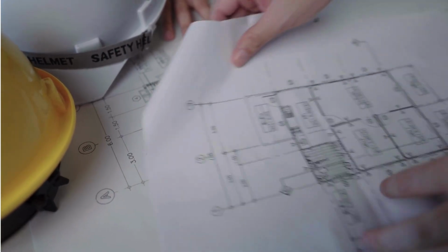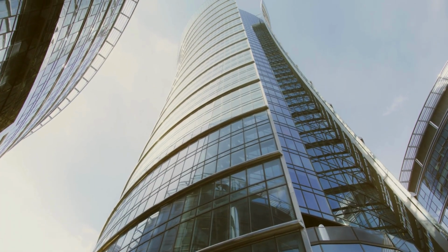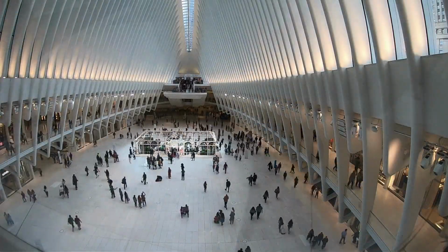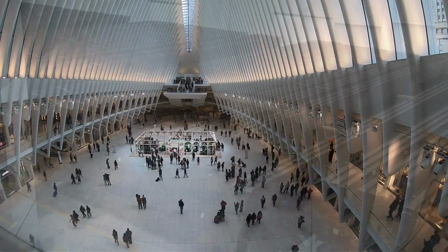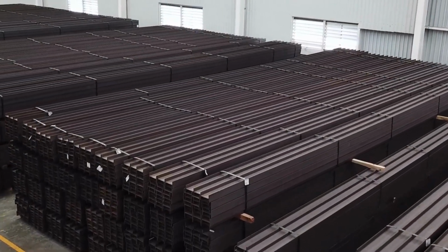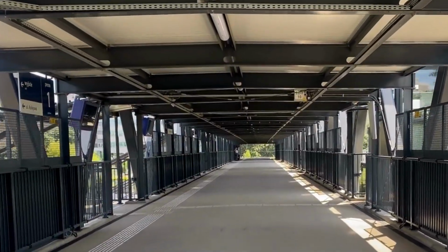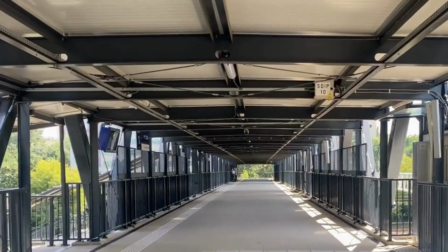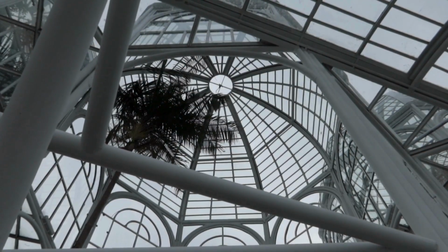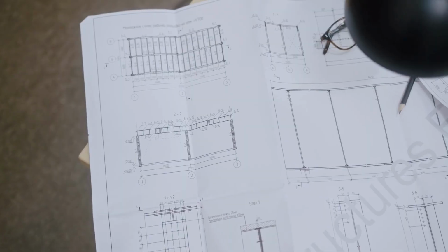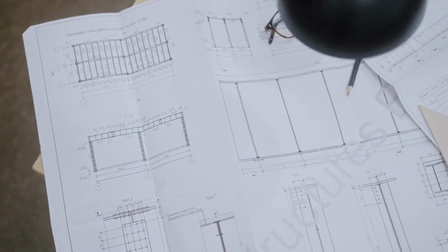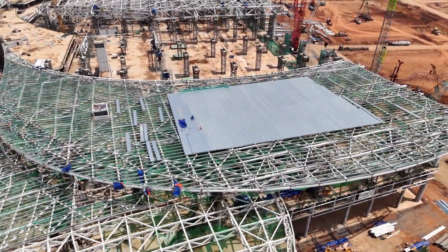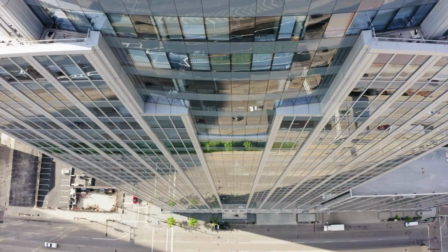As structural engineers, our job is to deliver safe, efficient, and constructible designs, all while working under tighter budgets and faster schedules. High-strength steels like ASTM A913 allow us to design lighter members and optimize material use, but they also require thoughtful specification. By understanding how to properly specify A913, you can take advantage of its benefits while also reducing your risk throughout the project.